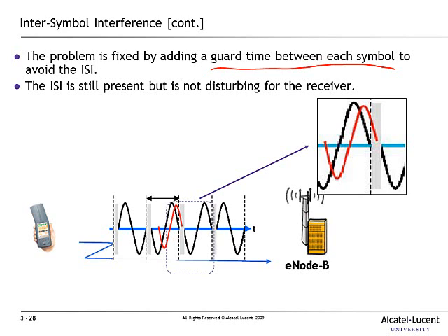We put this in so that this particular time which you see in gray here is referred to as a guard time. So even if a symbol was to arrive slightly behind in time, a reflected signal was to arrive slightly delayed in time, it will not have an impact on the next symbol that's going to be transmitted.